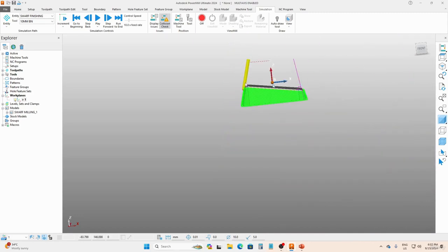That's why we have to use a certain type of machining operation. Rather than using the Z-optimized operation, which is totally different. In the Z-type operation, the cutting tool is normal to the Z-axis, or it follows Z. But here it just follows the surface and cuts down the material. So we have to use the multi-axis operation for that. So it's a totally different operation.